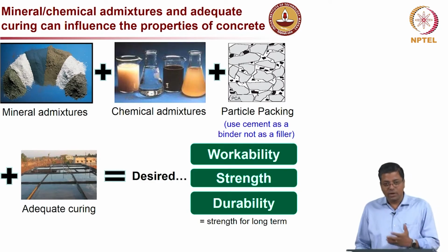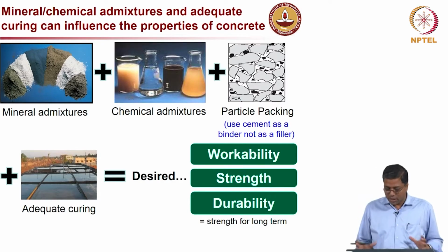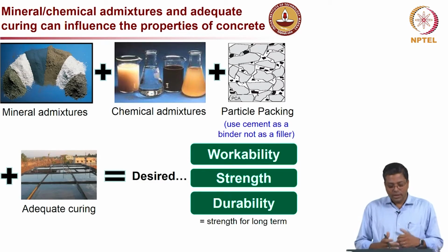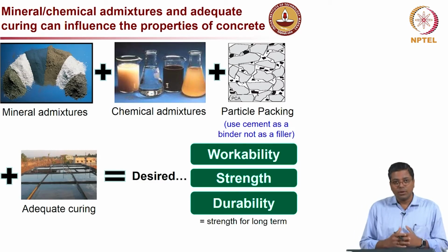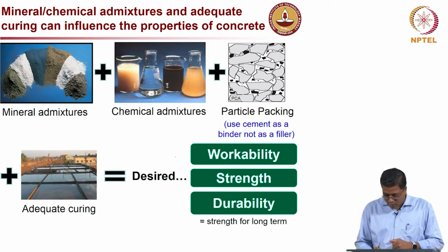In concrete we add different ingredients, mineral and chemical admixtures, then pack them very well, and then at the end you have to place and cure the concrete very well. That is very much important to achieve desired workability, strength and durability.